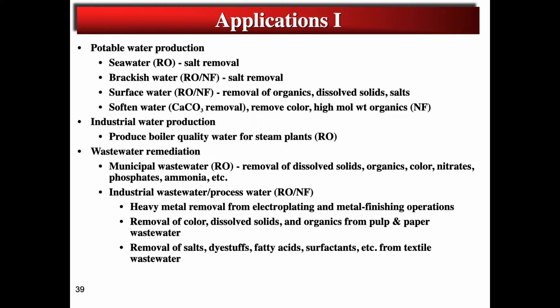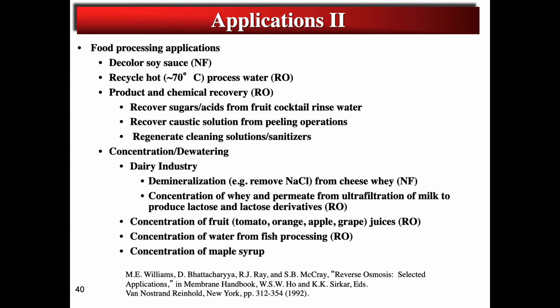And so what's done today is there's a series of injection wells that stand between the coast and a large fraction of that aquifer. As Los Angeles water flows into the wastewater treatment system, it goes finally through membrane filtration, desalination membranes. It's re-injected back into the aquifer to keep seawater intrusion from contaminating the aquifer.